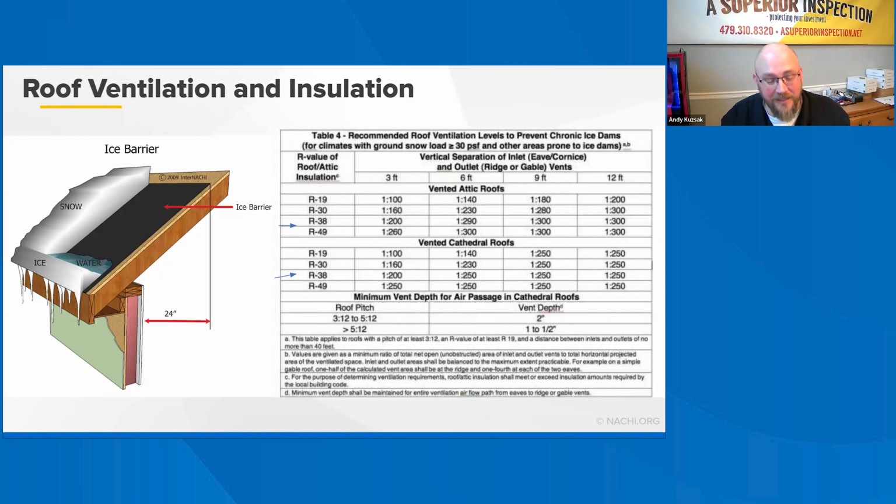And so what ended up happening is that because they put the metal roof over the top of a shingle roof, and they changed the structure, they did not change the ventilation. All that hot, humid air rose up to the ceiling, had nowhere to diffuse through, and so it condensed. It reached a dew point on the ceiling. It condensed, and it ended up raining inside of their home, causing thousands and thousands of dollars worth of damage.